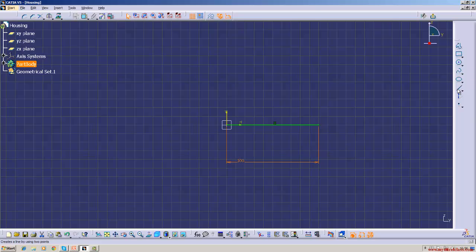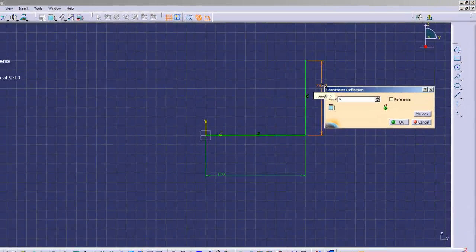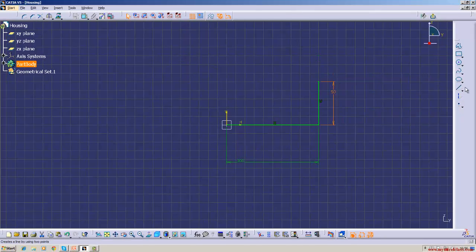Now, rectangle, see, if you imagine a rectangular bar with its section is rectangle 100 by 50. So, what we have to do is, first we draw 100 by 50. This is once again, we draw it 50. Click on this line, click on this, join.